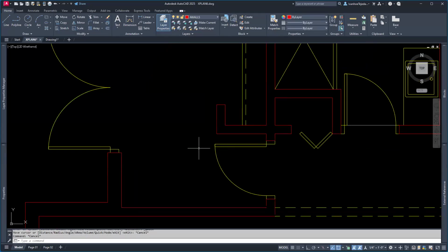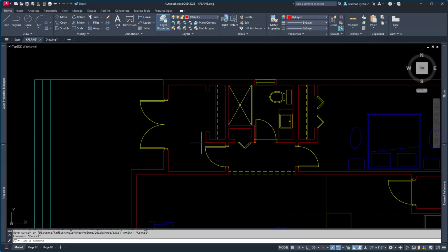That's typical because you have drywall on both sides, wood stud in the middle, and we go with a nominal dimension of 5. The actual dimension is probably going to be like 4 7/8, but nobody wants to offset 4 7/8. It's much easier to offset 5 and be done. So 5 it is. Go back to my drawing.